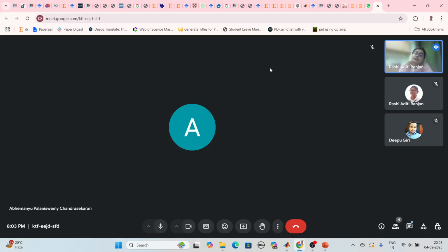It means even if I'm giving it zero initial energy, it is again going to oscillate on that limit cycle, because it's a self-excited system. The system has the capability to increase or decrease the amplitude, but it is always going to bring my system to that particular limit cycle. And for multiple degrees of freedom, it can have multiple self-excited cycles or limit cycles.